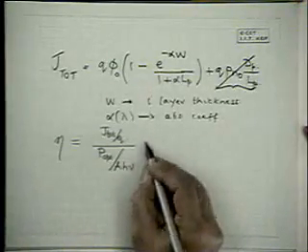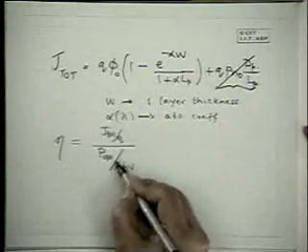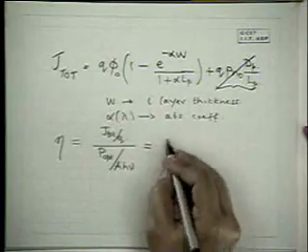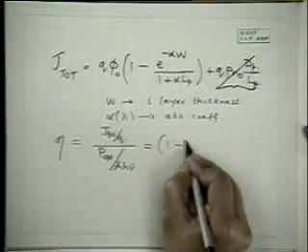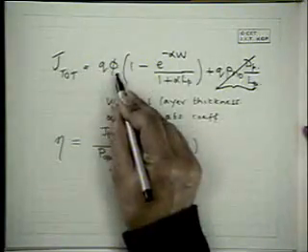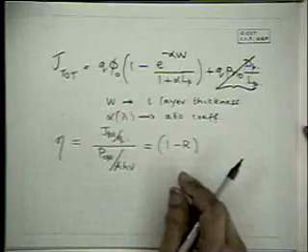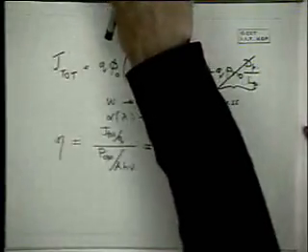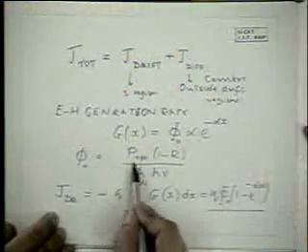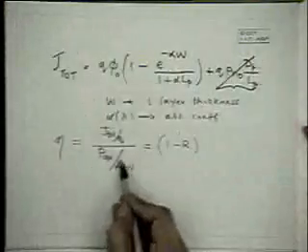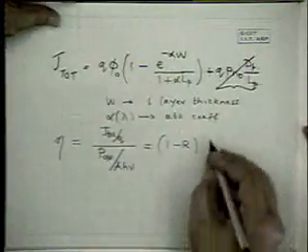And so when you divide by phi 0, which has this P opt A h nu, the relation is just 1 minus R. Phi 0 is P opt 1 minus R by h nu. So we divide by that, and we just get 1 minus R into this term.